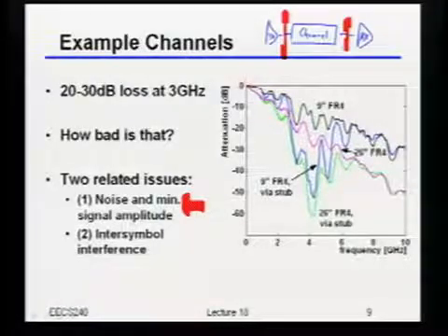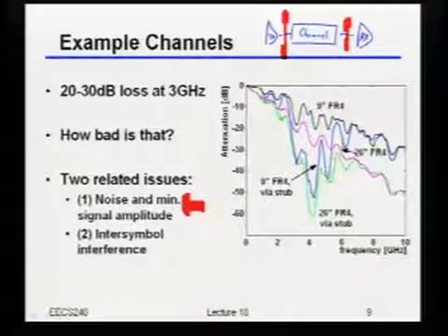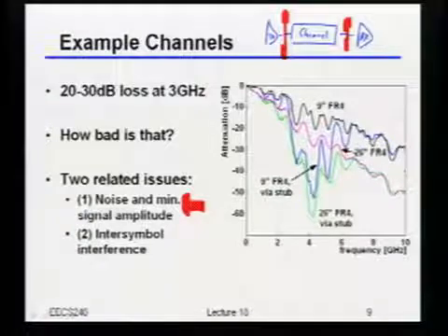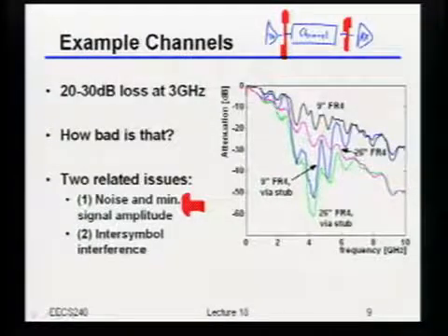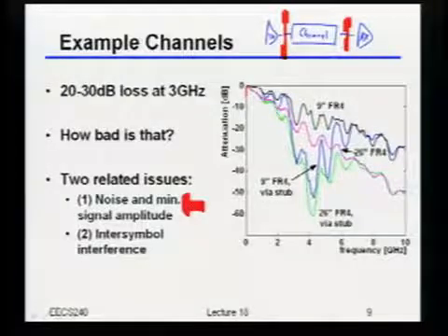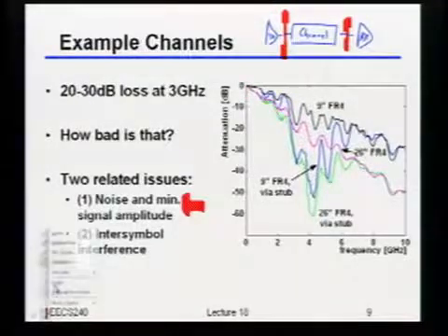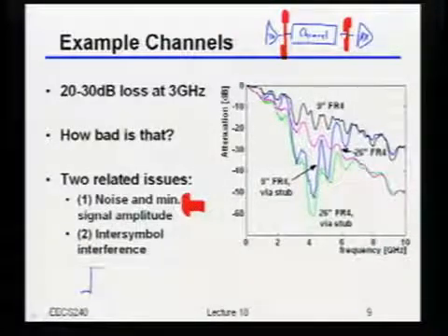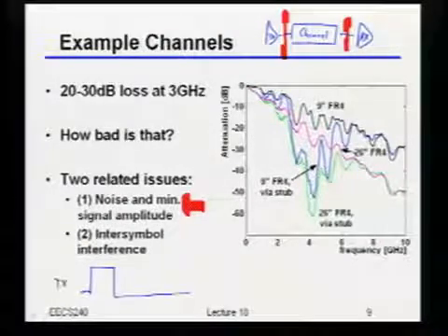If you look at this channel, it's not that I'm attenuating all frequencies exactly the same way. I'm actually attenuating the higher frequencies a lot more than I am the lower frequencies. In other words, this whole thing kind of looks like a low-pass filter. Well, let's just think about what would happen if I took, at my transmitter, let's say this is like